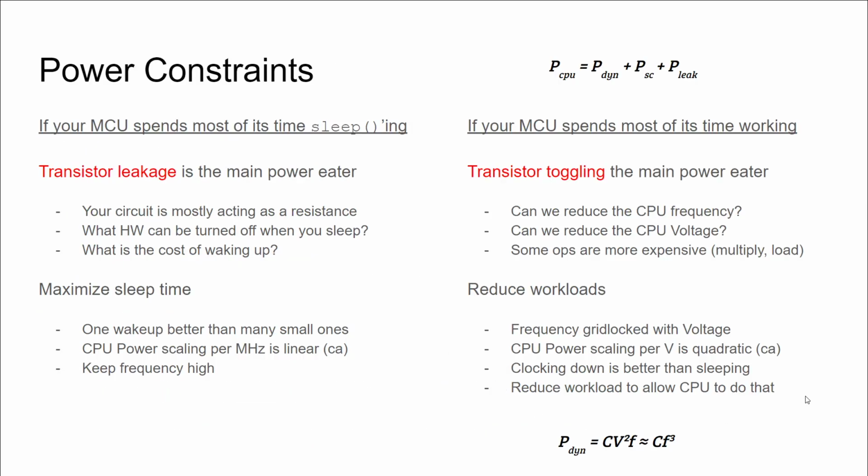In my biased opinion, power is probably more important than performance. We can always make hardware or software that is faster by just increasing the clock speed of the MCU it's running on. The only thing preventing us from doing so is the power budget. If you use more power than you can dissipate heat, the MCU will literally burn, and this is especially important for mobile devices. You don't want a cell phone that is literally too hot to handle.